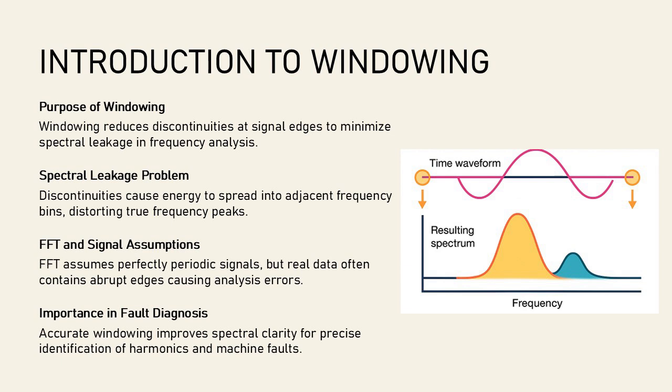Windowing is a critical concept in vibration analysis and signal processing, particularly when using the fast Fourier transform, FFT, to convert time domain data into the frequency domain. The FFT assumes that the time waveform being analyzed is perfectly periodic and continuous. However, in reality, the captured time record often does not start and end at zero amplitude, which creates discontinuities at the edges of the sampled data.